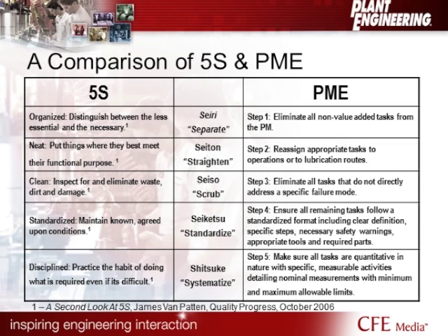Now the last one, systematize. In here, we're going to make sure all the tasks are quantifiable in nature, and they have specific measurable activities. So instead of asking someone just to check the pump, now we're going to, based on the previous step, standardize that and tell them exactly what specific failure modes they need to look for on that pump, and then try our best to make those quantitative.